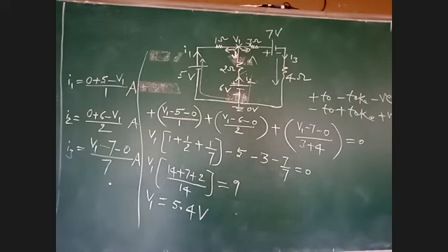But when you are determining the actual current, forget about the assumed currents. Go for the actual direction of the current. These 2 points you remember. While determining node voltage, consider only assumed directions. If you remember this point, it will be very simple. Otherwise, it will be confusing.